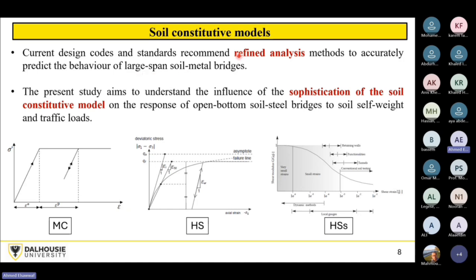It only recommends that if you are going beyond a 10 or 11 meter span, you need to do refined analysis, which means that you have to do finite element or finite difference. So if you must do finite element modeling, we have to see which is the best model that can be employed to simulate the behavior of the soil.